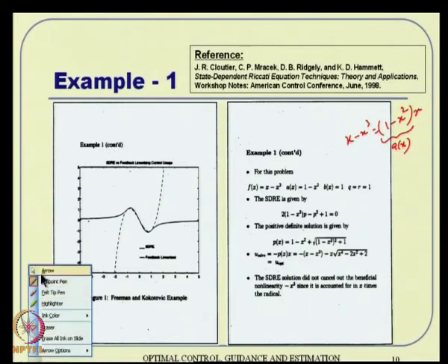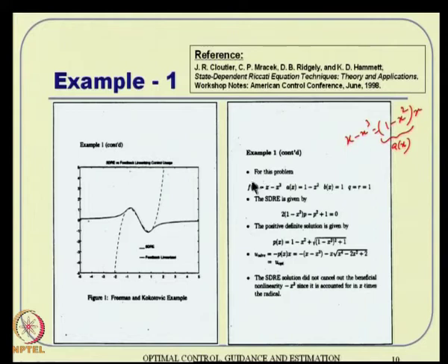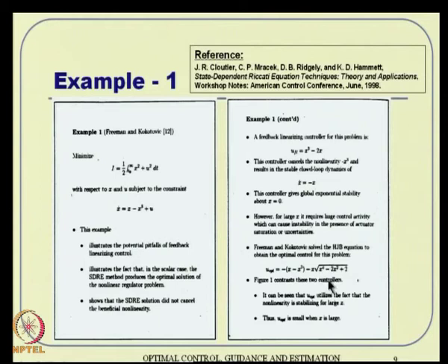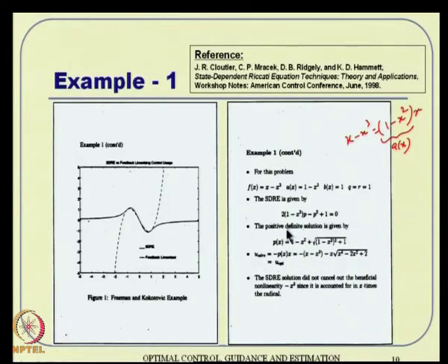Okay. Once you have that, you can put it back into the Riccati equation, and the Riccati equation will throw some equation like this, and hence you will get a solution for p, and then you get a controller which is minus p times x, because b is 1 here. So, it will turn out to be exactly same as what we have seen here actually. Remember, this comes from the Hamilton-Jacobi-Bellman theory. This can be derived that way, but if you just substitute this and then put it into the Riccati equation and then try to solve for a controller, it happens to be exactly same actually.